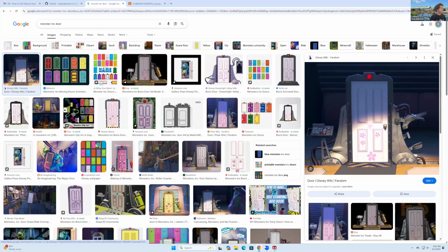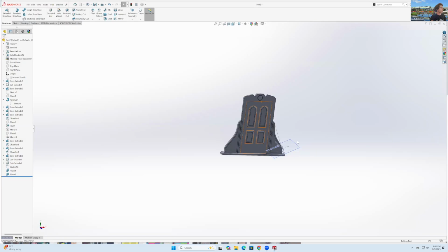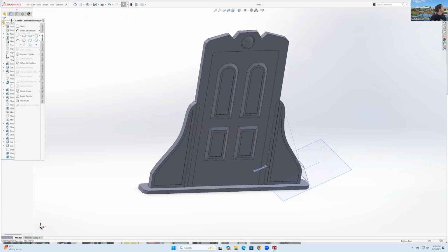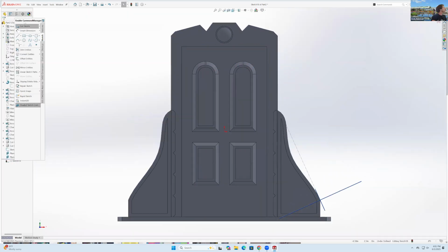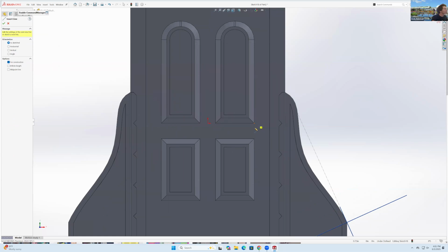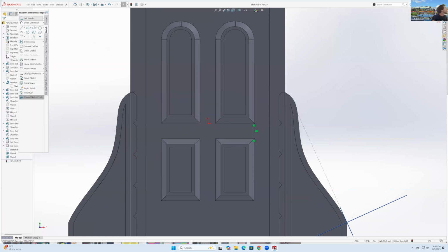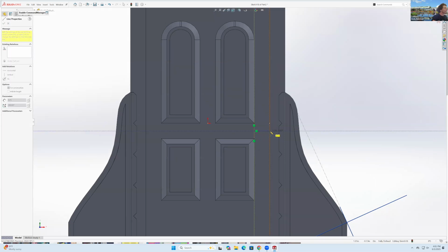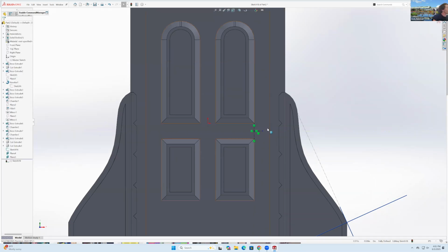It's right there, right? So I would go here to sketch, this facing here. Oh, you're gonna revolve the whole thing, yes. So I do a little center line that goes all the way like this. We'll take the phone call later on that one. And I'll just draw a line that's gonna go up to there.